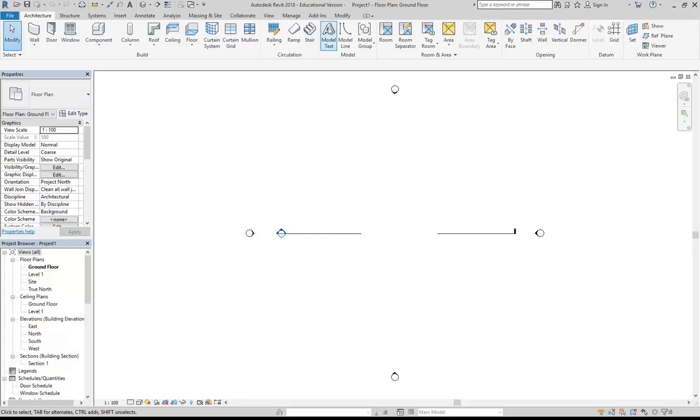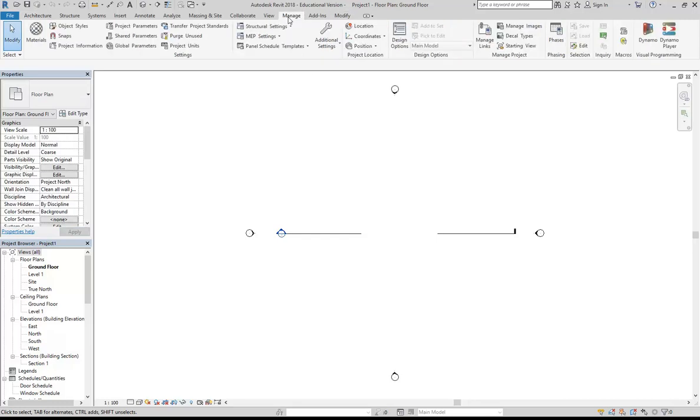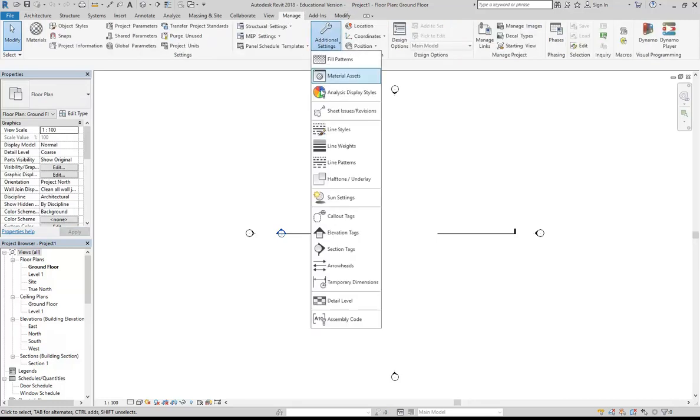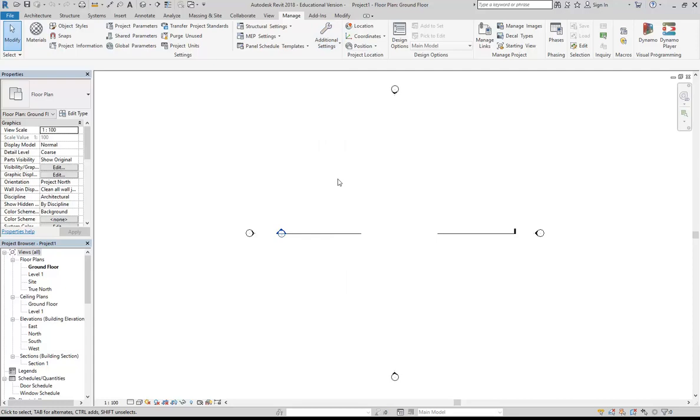to all of you. So if you use the default line weights, your drawings won't look very good. And you probably have been all using the default line weights up until now and just had very heavy lines in your plans and sections especially. So make sure you're aware that you can customise the line weights, and that is the one thing that I tend to change from that default template. Otherwise, I think everything in that template's pretty good.